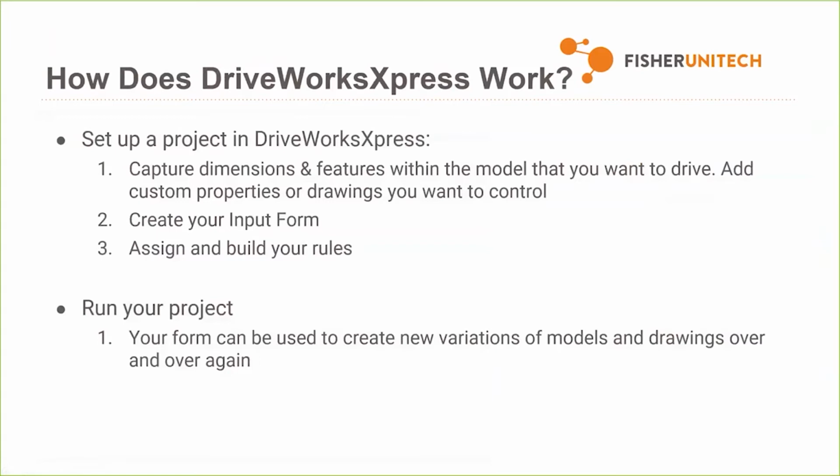So how exactly does DriveWorksXpress work? Initially, you have to set up a project in DriveWorksXpress, and this is all done internally within SolidWorks itself. It's an add-on for SolidWorks. Once you set up that project, you have to go ahead and capture dimensions and features within the model that you want to drive. So if there's any sort of dimension, maybe a length dimension that I anticipate having to change, I would go ahead and capture that dimension. And if there are features that I may or may not want to have, depending on that variation, I would capture the feature itself. From there, I can also add custom properties or drawings that I want to control as well.